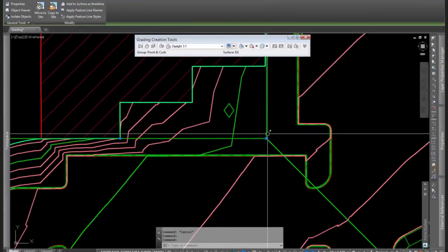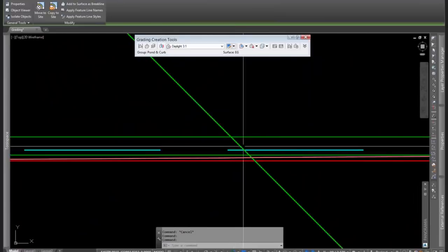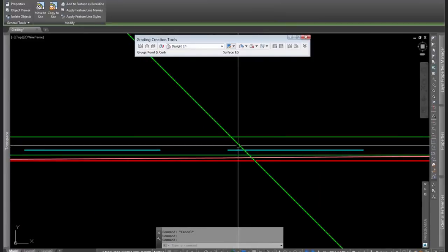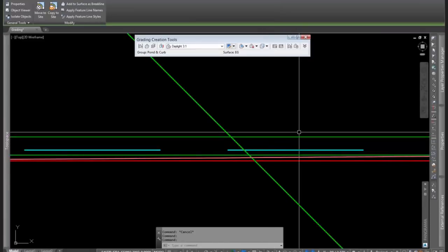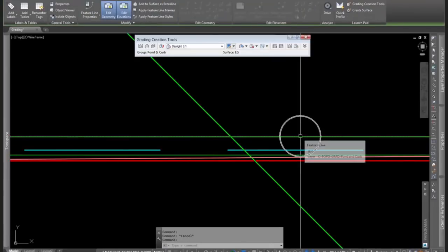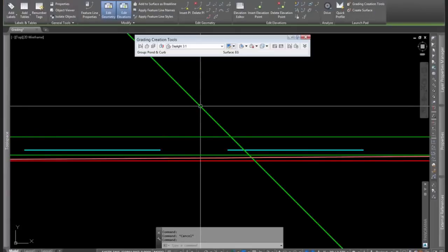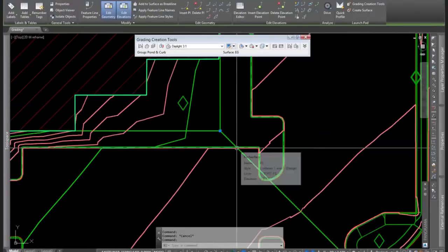And even worse, these drainage feature lines, if they cross this grading object right here, this is a curb face and a curb top, a sharp grade change there. Feature lines will interact with grading object created feature lines as well. So this line right here, that's in fact like an embedded feature line. So if that's in the same site as this feature line, which is 6 inches below it, they're going to interact and assume the same elevation. We don't want that.